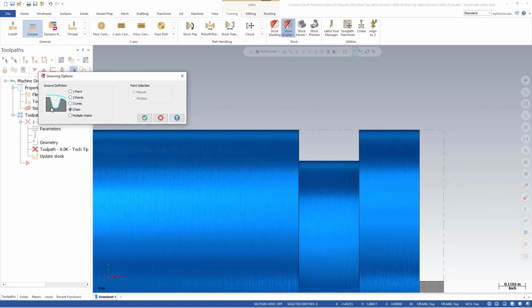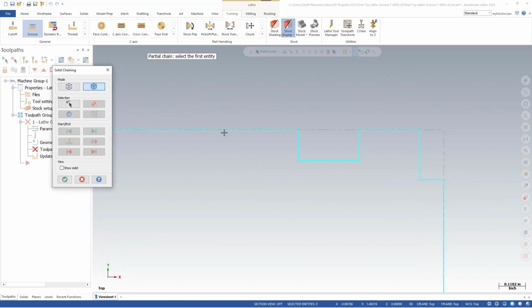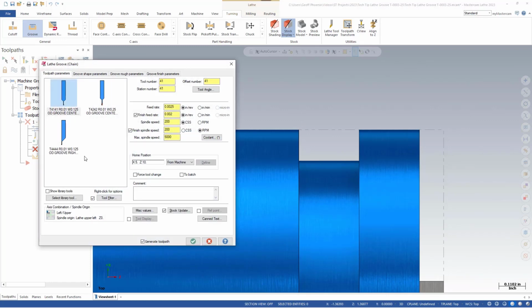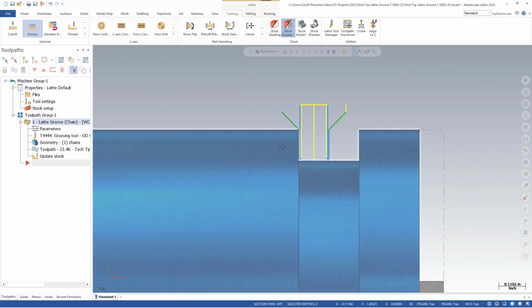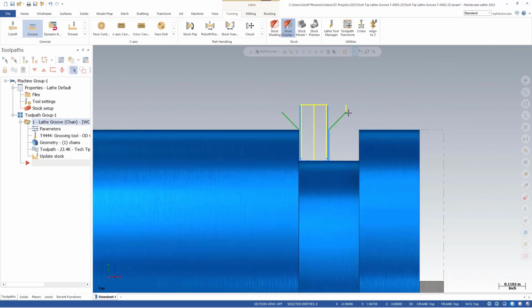This is our geometry selection. And anytime I've ever done grooves where it's been modeled into the solid itself, I always select chain selection. This is well and fine, but the problem is that we're now locked into the shape of that groove. Let's say the engineer intended to have this be deburred on the surfaces here. Having a sharp corner like this will leave a burr and make it very hard for your deburr department to come in and clean those burrs up. So I always like to add little radii here.